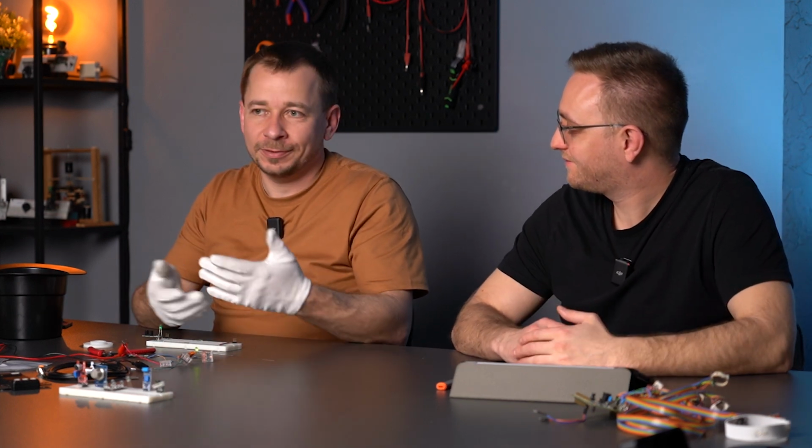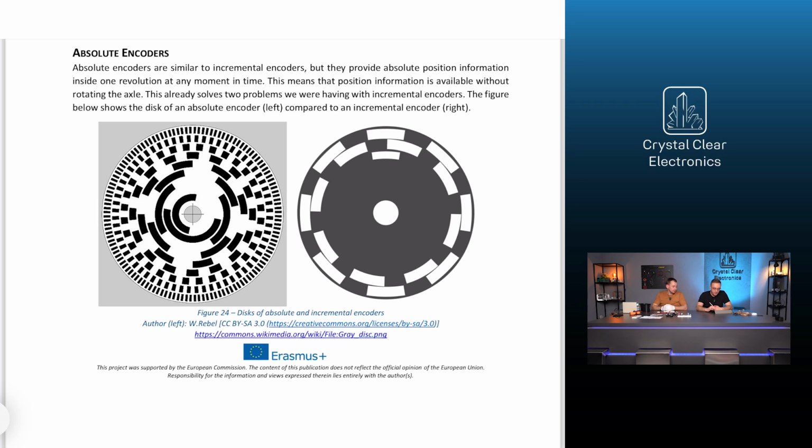Yes, but we also know that there is always another way with some benefits and drawbacks. Yes, of course, such as the absolute encoders. Absolute encoders are similar to incremental encoders, but they provide absolute position information inside one revolution at any moment in time. This means that position information is available without rotating the axle. This already solves 2 problems we were having with incremental encoders.